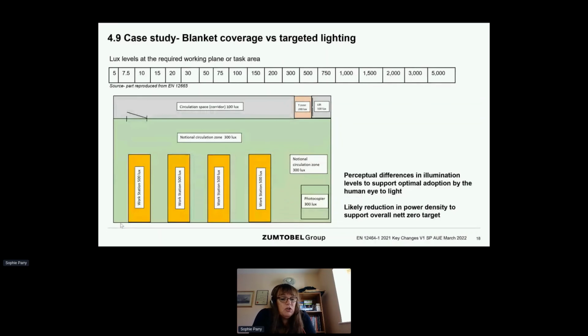So again, you could set the second lighting scene to 200 lux and try it out at commissioning if you've got the luxury of time, see how you get on with it. And if you don't like it, you could move it back up to 300 lux, or even set 3 scenes. So it's just a simple matter of selecting the ones that were preset and then locking them off. So it can only be that.